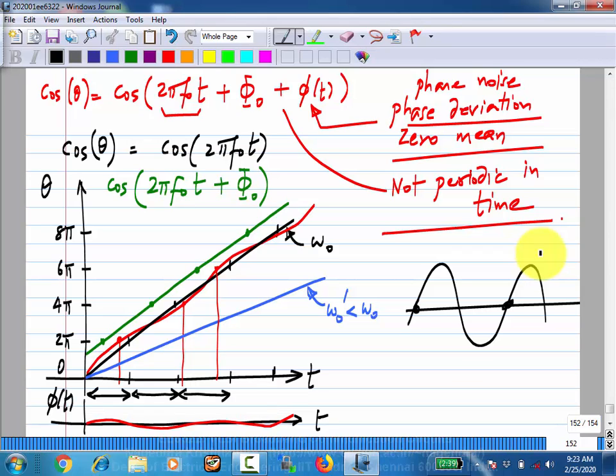So you can measure the phase only by looking at the position of the edges. But for a lot of analysis, it is convenient to think of this phi or theta as a function of continuous time. So that's what we will do. But sometimes you may have to use samples of this to look at what is happening at the point of interest. So what you really want is essentially the ideal edge position is here, and the actual edge position is there. You just want to know the phase deviation, right? Is it okay?